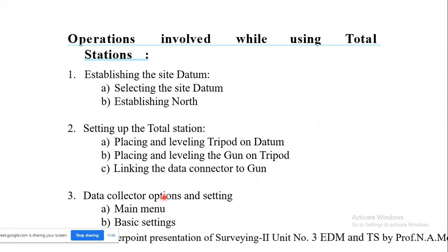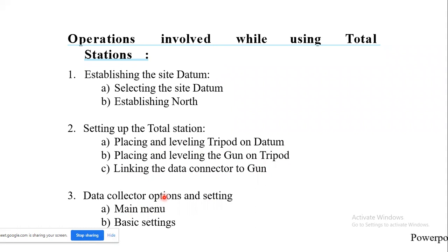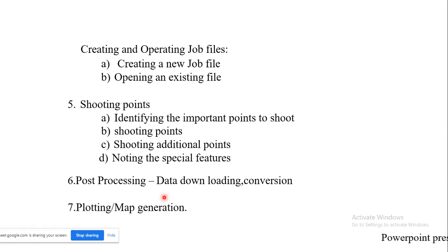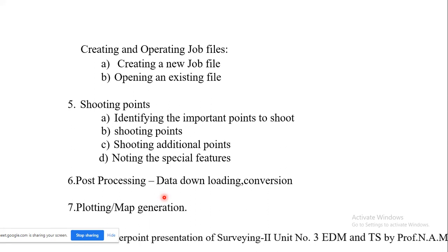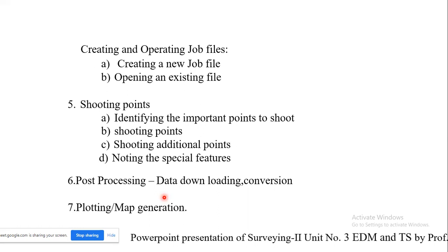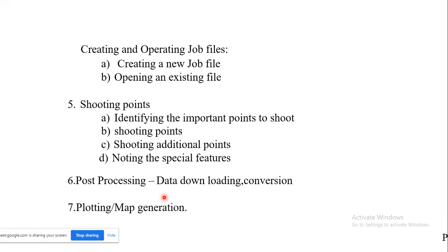These are nothing but the basic requirements which you are supposed to do when you are going to handle the total station instrument. Then create and operate the job files. Whatever work you are going to do, suppose I am interested in measuring the area, for that purpose I will be requiring to store all the points that I'm going to collect, whether it is a horizontal distance, horizontal angle, vertical angle, or vertical distance,